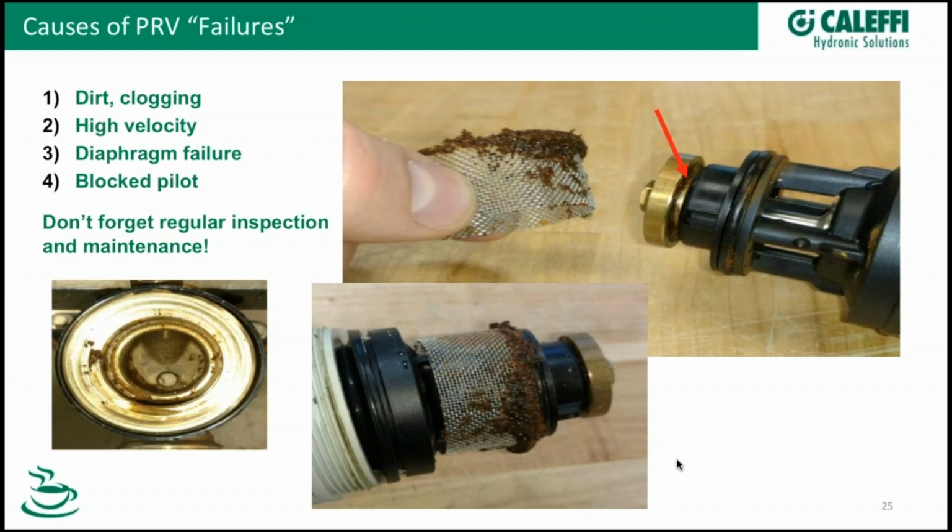If you set it at one pressure and you look at it 15 minutes later or the next day, and it's beyond the pressure that you set it at, which you can still see in your window on the valve, that indicates that you probably want to take that apart and check to see if you got some debris, Teflon tape, or dirt. I can see on this application, anything can get in there and cause that problem.